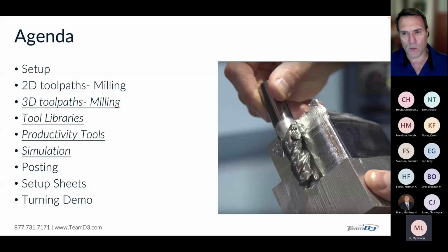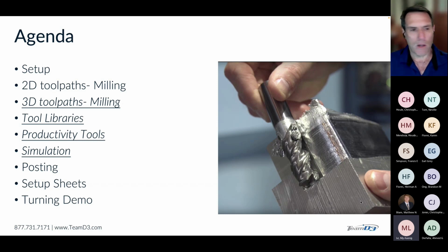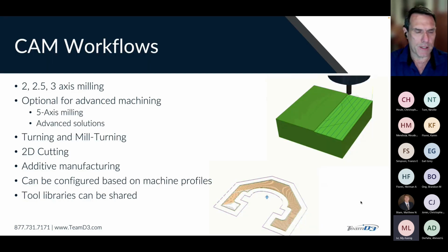You can sync up those tool libraries and what tools are in what position of the machine and what options are engaged so that as people start programming, they already know they're getting the right tools with the right functions. And then we'll also take a quick look at some setup sheets.